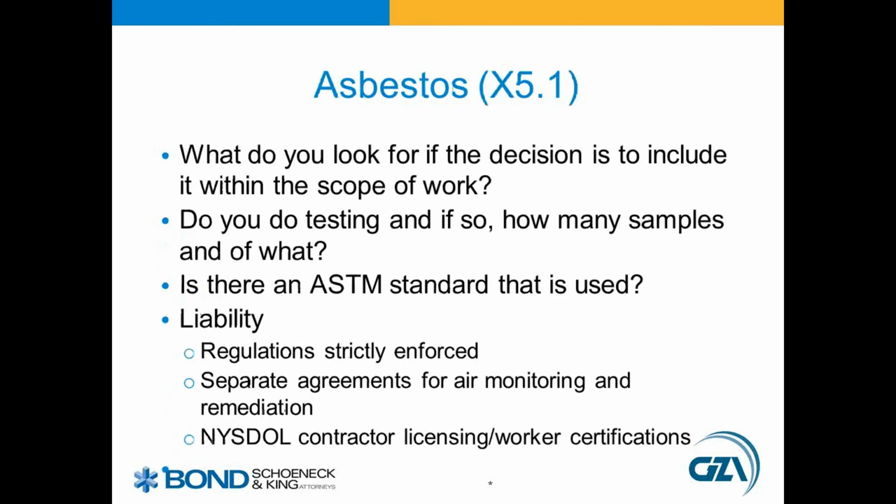Asbestos can be one of the more costly remediation jobs when deciding to rehab a building. Asbestos was incrementally banned between 1973 and 1978. So the general rule of thumb is if your building was built after that, you should be free of asbestos. But if it's before 1978, then it's recommended to do an asbestos inspection. Suspect material can include pipe insulation, floor tiles, wallboard, and fireproofing. Fireproofing was one of the main benefits of using asbestos in building materials.